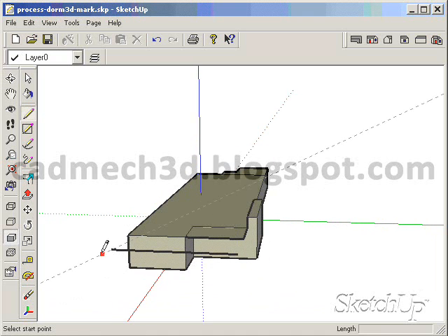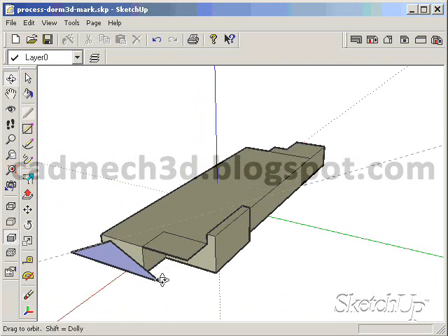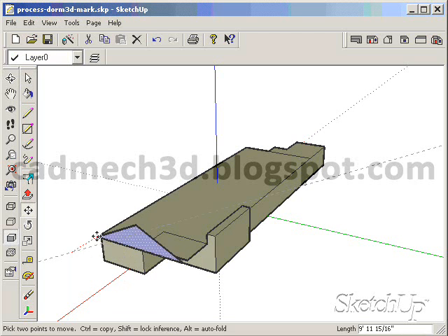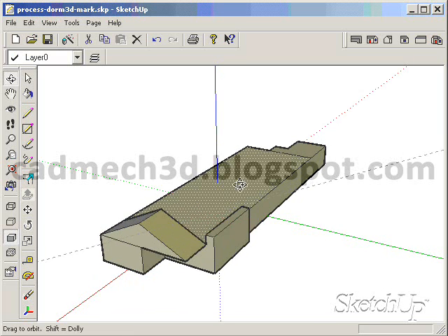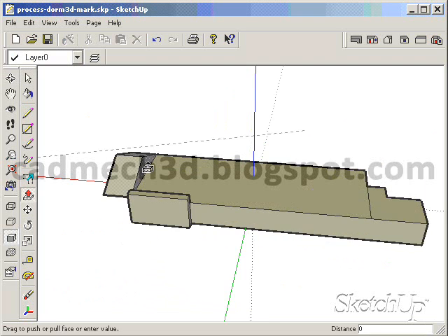Now I have a midpoint for the entire width that I can infer from up to the roof slope construction line. This draws in the gable end. We can now select this surface and move it back to the face of the building. Using push-pull on the triangle, I can extrude the main roof as a volume over the majority of the building.